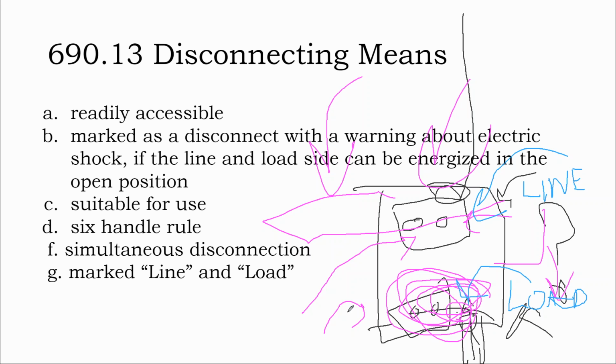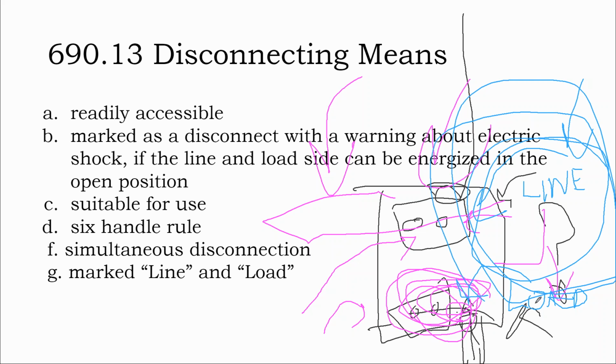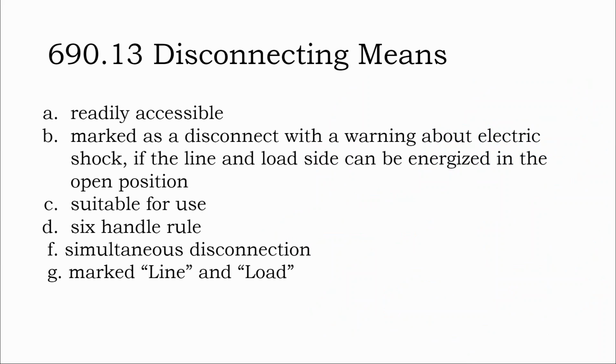And in this case, even though you have the grid, which is obviously a supply, you might also have the solar array, which might not have any load circuits on it. So you say, okay, well, which goes into the top? They're both supply. The grid's a supply, the solar array's a supply. Which one lands on the top of the disconnect switch? The answer is the supply that's always on. The grid side goes into the top. The primary side goes in the top.